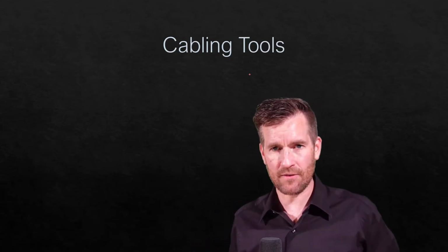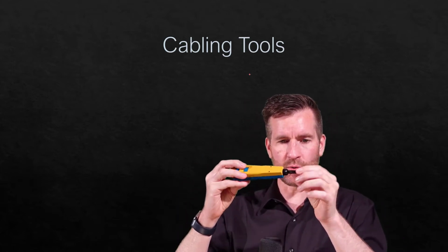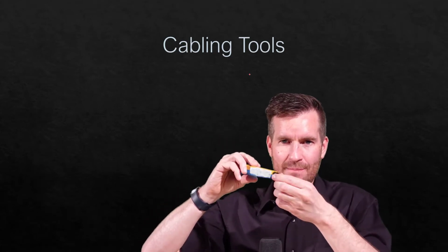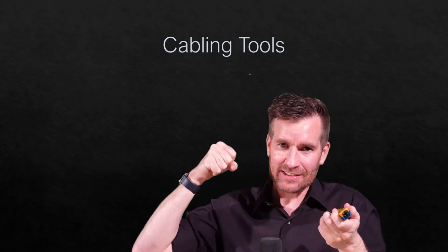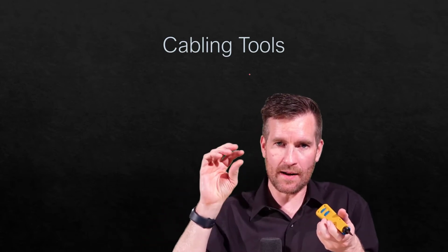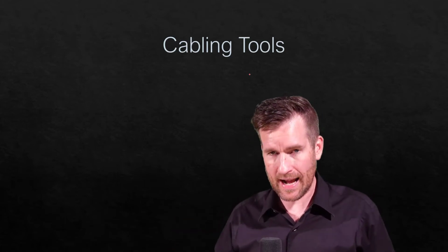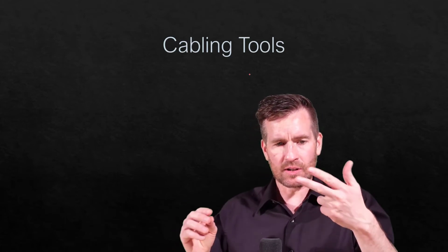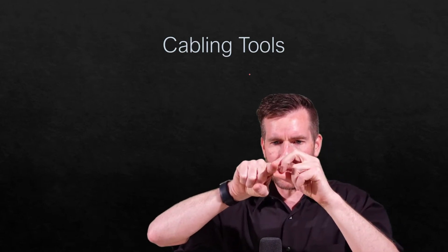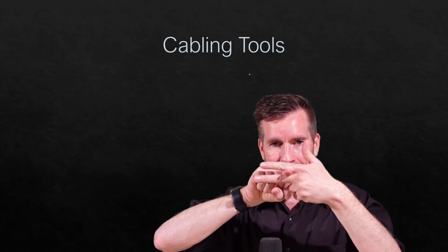One thing I haven't covered yet is this punch down tool. So this is a punch down tool. The reason why it's called the punch down is because you push on it and it makes a little clicking sound. It's actually kind of a little hammer that just punches down on it, and it puts just the right amount of force on those cables. What it actually does is, there are little conductors that the cable goes into, and it peels away the insulator around the conductor and then makes a connection there.